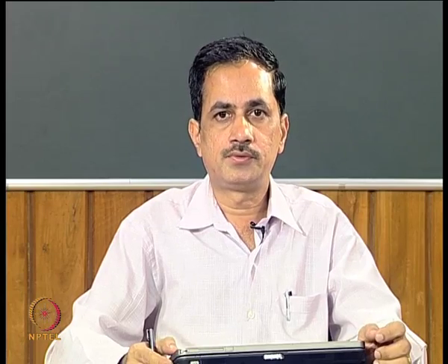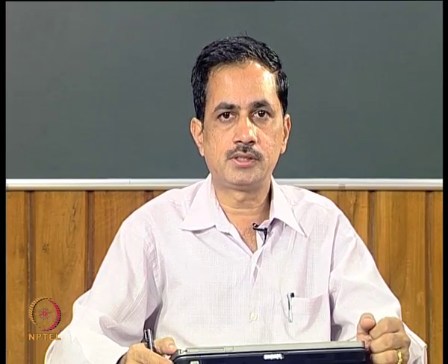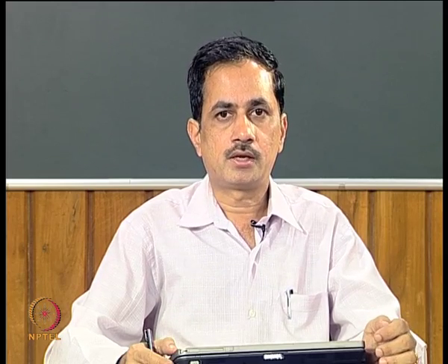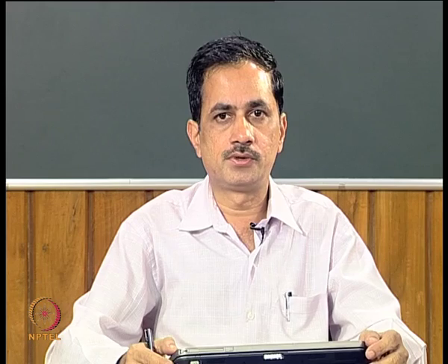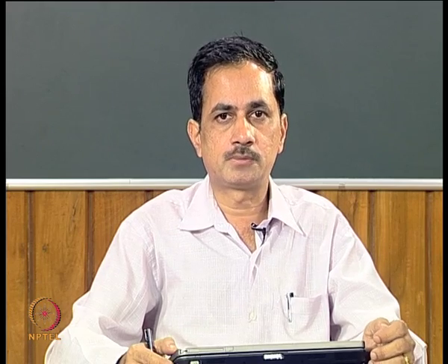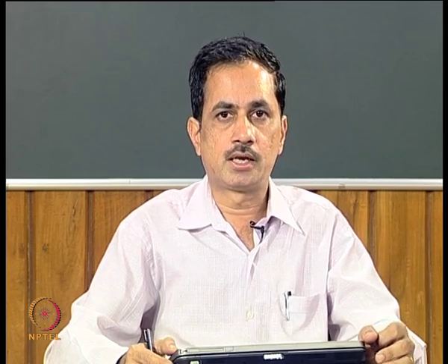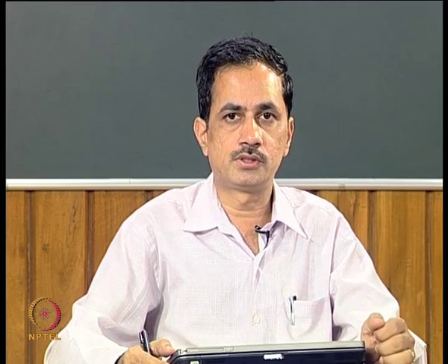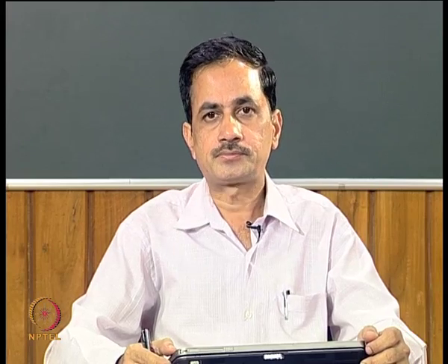In today's lecture we have seen how flexible rotor balancing is different as compared to rigid rotor balancing, and once we differentiated this, we introduced the concept of modal eccentricity in line with the modal mass and modal stiffness which we introduced in the previous lectures.